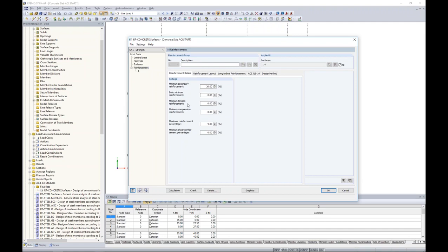You can see here my reinforcement ratios on this first tab. There are a couple of defaults already set. You can change these. The ACI code tells us that maximum reinforcement percentage, basically this is to avoid brittle flexural behavior in case of an overload type situation. In the newer ACI codes, essentially, they've gone away with the reinforcement percentage, but now are more focused on the net tensile strain of the concrete being greater than or equal to 0.004. So what the code's telling us is that you can essentially mess around with these percentages as much as you want, as long as those net tensile strain limits are met. 7.3.3.1 and 8.3.3.1 from the code refer to both one-way and two-way slabs, and they both state the same thing, that net tensile strain must be met.